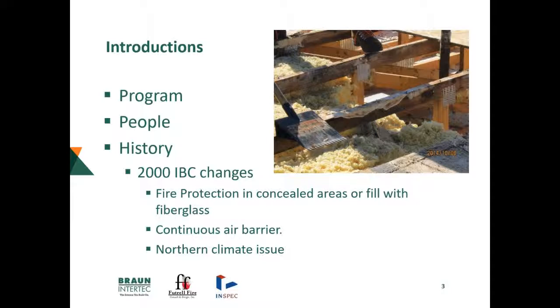So today what we've got is Scott Futrell from Futrell Fire Protection, and Gary Patrick, Executive Vice President of InSpec. We've all gotten together here and looked at this. The program came about because I got a call from Scott Futrell about changing from a sprinkler system to fill in the cavity with fiberglass, and he was looking to have the fiberglass tested. Well, that kind of led to the unintended consequence of changing the dew point in the assembly, which would have led to deterioration of the roofing.